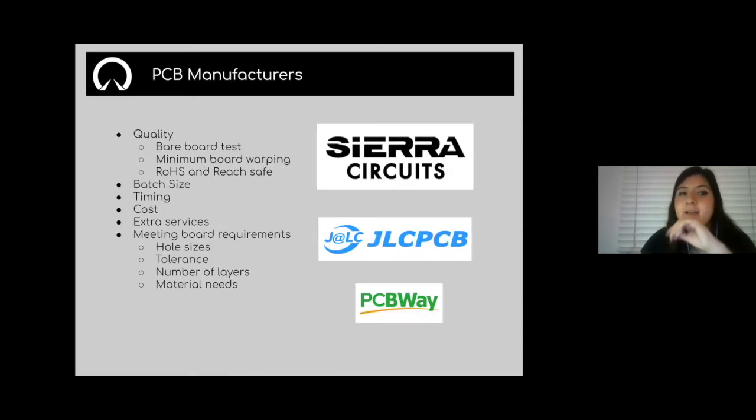All right, so now the tips for the PCB manufacturing. Some key things to consider when picking a manufacturer is, one, quality. Are the holes going to be drilled correctly? Is there minimum board warping? Are they going to perform a bare board test for you?